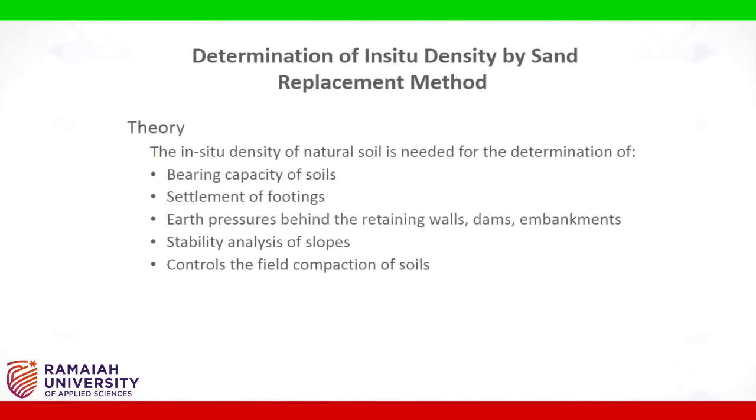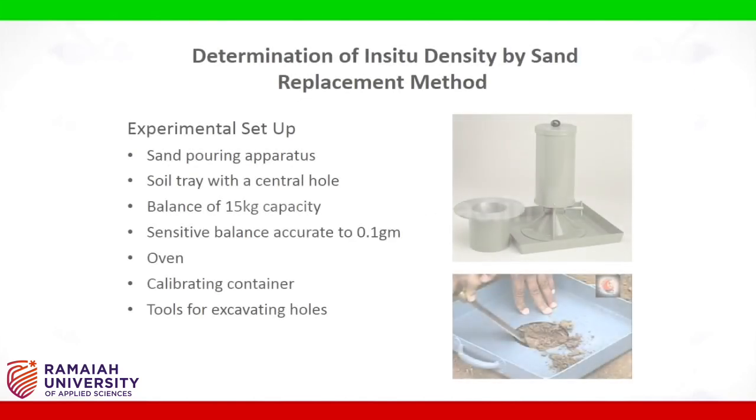The in situ density of natural soil is needed for the determination of bearing capacity of soils, settlement of footings, earth pressures behind the retaining walls, dams, embankments, stability analysis of slopes, and controls the field compaction of soils.